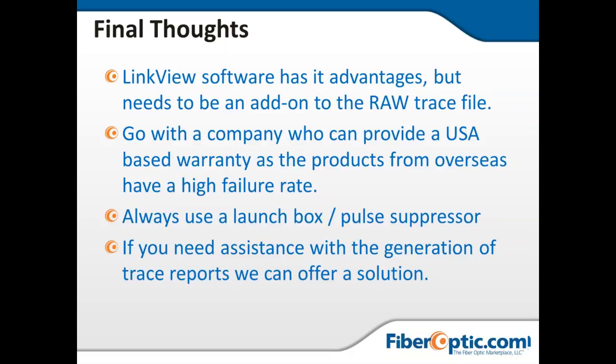And then if you need any assistance with generation of trace reports or things of that nature, that's another thing to consider is who's going to be doing that trace analysis. It's one of the things that we offer as a company. People send trace files to us, we clean them up, and do bidirectional analysis. But if you're going to request that a partner do that type of service for you, make sure that you're picking a platform that has a SOR type of file format that it can be exported to, because that's kind of the universal standard out there. Otherwise, you might have some sort of compatibility issues that may arise.